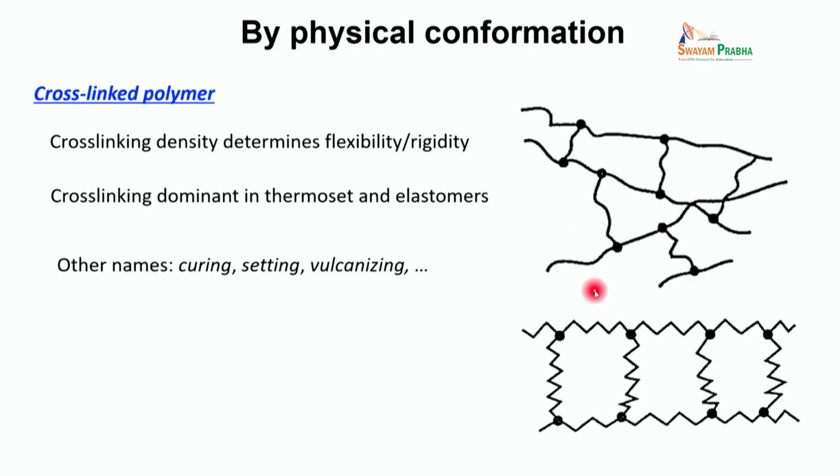Here I have given an example where we have two polymer chains, they are cross-linked through a cross-linking agent. Here we have a flexible network, and there are a few cross-linking points. This is a cross-linking point, this one is a cross-linking point. Typically you will see this in a vulcanized rubber. Okay. And this is an example of cross-linked polyethylene, right.